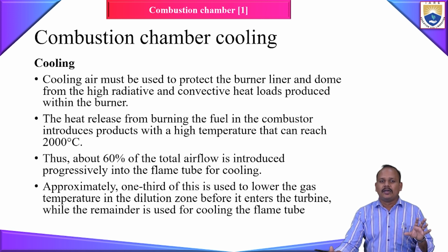Any combustion chamber we design will have something called hot time. Hot time, or hot hours, means how much time this combustion chamber is exposed to the combustion. Based on that, the lifetime of your combustion chamber will keep coming down as your hot time increases. Why? Because of the creep problem. So if I want to increase the life expectancy of my combustion chamber, it should be provided with a proper cooling setup.